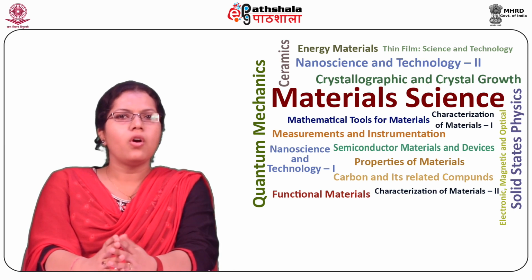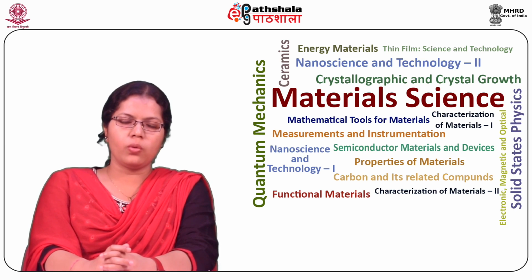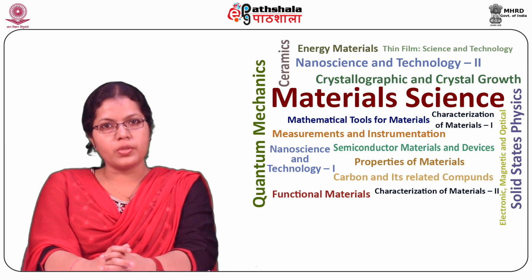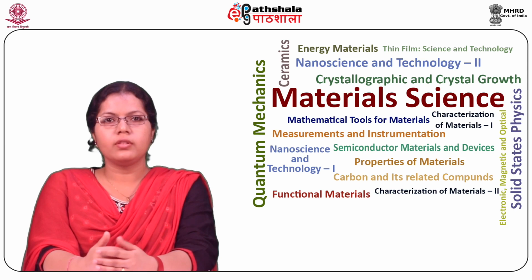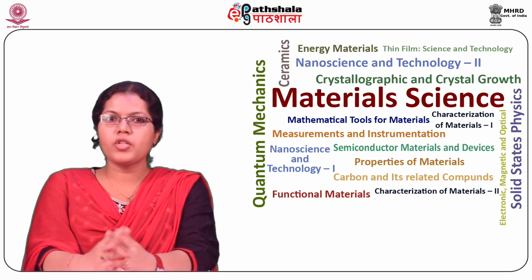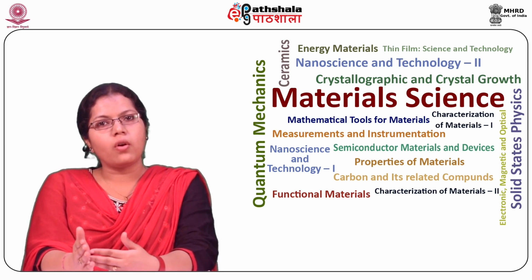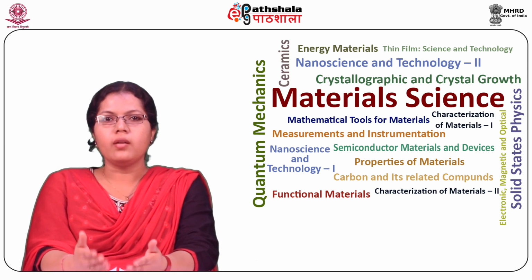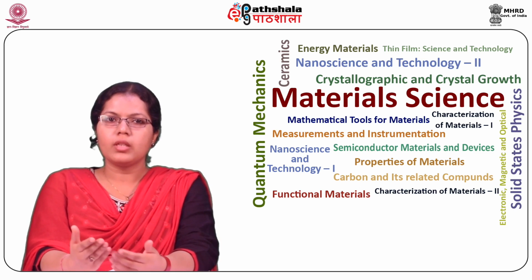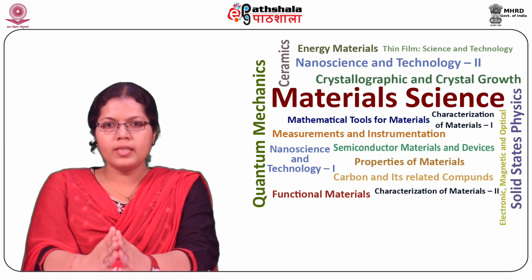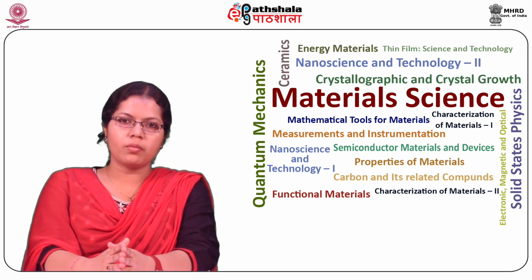Environmental parameters also play a significant role in transducer selection. It includes consideration of the ambient temperature for the measurements. Second, the corrosive or non-corrosive atmosphere where measurements are to be carried out. Third, the shock and vibration to be withstood during the measurements.